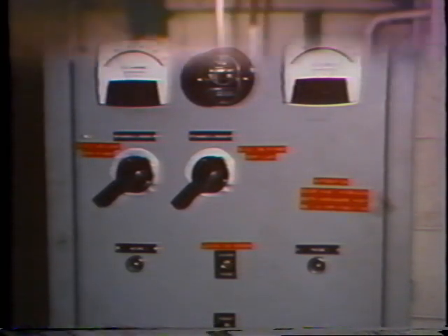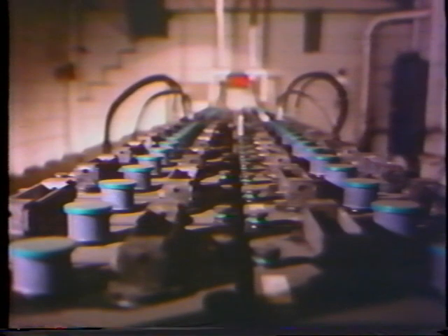Okay, since we know that a battery isn't much good unless it's charged, the next logical question is, what do we do to charge a battery? What do we use? Well, the most common type of battery charger is a constant voltage charger like this one. When you use a constant voltage charger, you set the charger to the normal operating voltage of the battery you're hooking it to. The charger will then keep the battery charged to that voltage, and you won't have to worry about accidental overcharging.